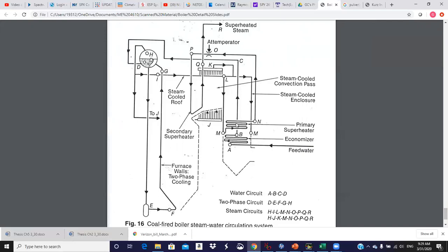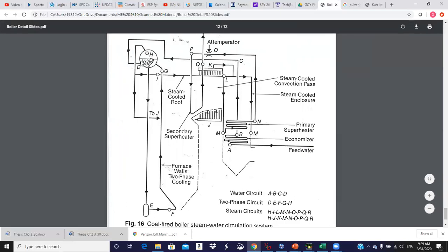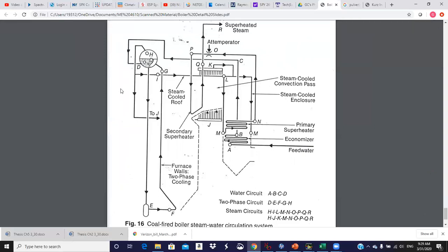a pipe. And then from B, we go up to C and over to D. So basically, we're just going to the steam drum. Okay, so that's the feed water path from the last feed water heater into the economizer, out of the economizer, and then it's piped over to the steam drum where it enters, and that maintains drum level and keeps that reservoir of water up at the top of the boiler to make sure that we don't boil those tubes dry, which would be a bad thing.